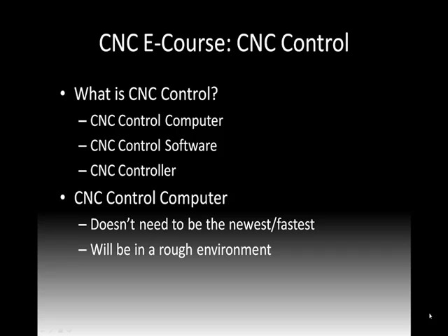And also keep in mind that your control computer is going to be in a pretty rough, rugged environment. So I think of my CNC plasma cutter, puts out quite a bit of smoke and dust, and that goes to the computer in some way, shape, or form. Now, you can do a number of things to keep it away, but you know what? A lot of it ends up there. Don't kid yourself. So usually what I recommend is to go with something that's a lower cost unit that you really won't get too mad about if it gets damaged out in your shop.